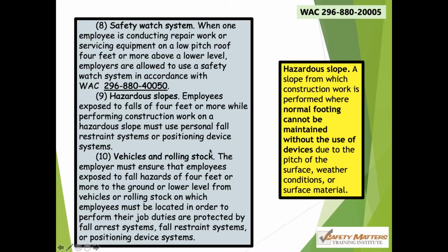And now we get into that really interesting thing right here called vehicles and rolling stock. Remember, if you go back to the definition of a working walking surface, we stripped out 45 by 45. We stripped it out. And so that opens up everything except for it said other than ladders. Vehicles and rolling stock. The employer must ensure that employees exposed to fall hazards 4 feet or more to the ground or lower level from vehicles or rolling stock, on which employees must be located in order to perform their job duties, are protected by fall arrest systems.